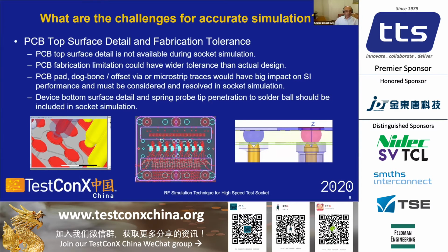When we see a problem like that, the top surface PCB has some exposed via, exposed traces, microstrip traces, solder mask. We need to capture all of this in the simulation, or at least advise the customer by making some changes or recommendations, moving some traces away from our socket or probe head hardware, and make sure that we optimize all the footprint for this particular test board.